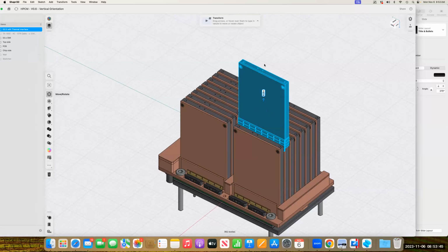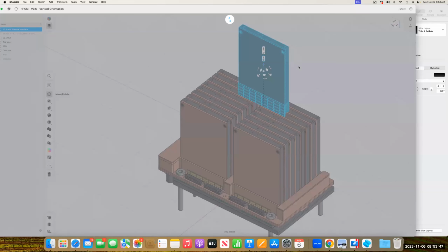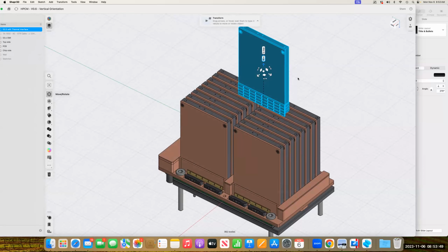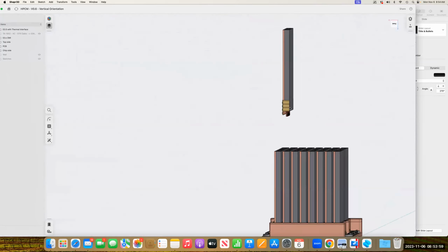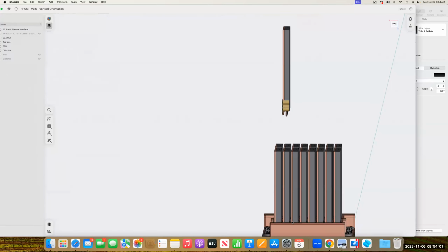Chris Blackburn gave me the idea that this would be a better approach. We had the thermal gaskets actually in the manifold, but it was better to put them on the modules. So the idea would be, as you insert this module in, you get the alignment. So you wouldn't have any tilting forces that are going to tear the connector off the board, like if it wasn't guided.